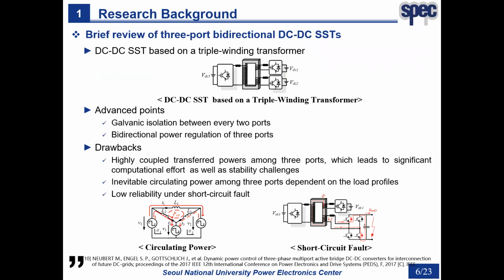To address this issue, the most widely accepted solution is the 3-port DC-DC SST based on a triple-winding transformer. It can realize the galvanic isolation between every 2 ports and at the same time realize the bidirectional power regulation of 3 ports.